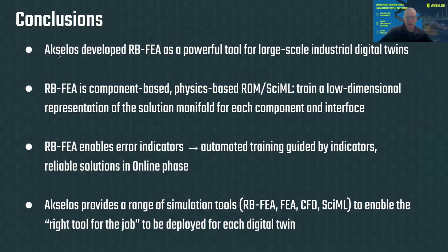I'll just give my conclusions. So Akselos developed RBFEA as a powerful tool for large-scale industrial digital twins. RBFEA is a component-based, physics-based, reduced order model approach, or relatedly scientific machine learning approach, because we train a low-dimensional representation, a reduced basis representation of the solution manifold for each component and each interface. RBFEA enables error indicators, like I've talked about quite a lot, which means we can automatically run training guided by indicators, like, for example, the greedy algorithm, but similarly at the system level. And it gives reliable solutions in the online phase.